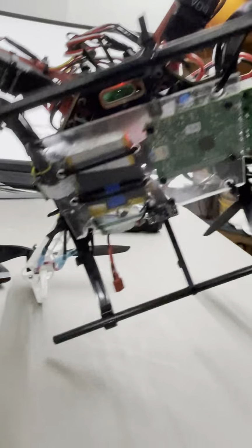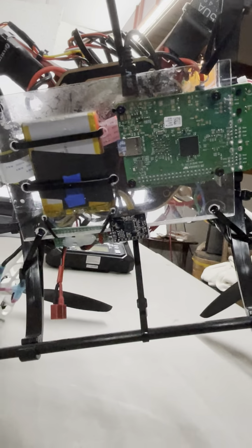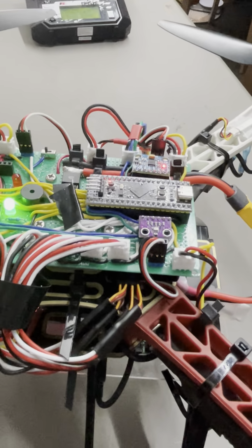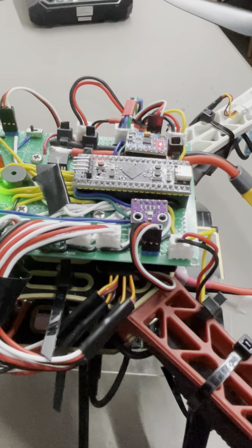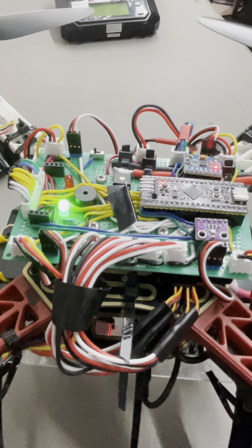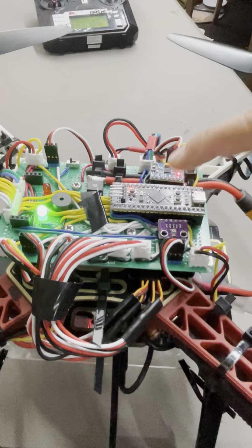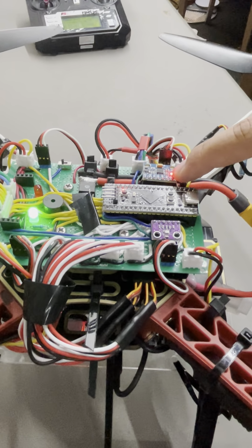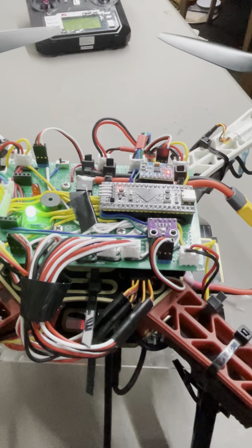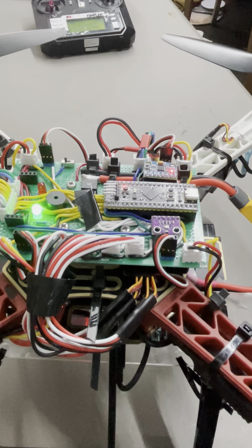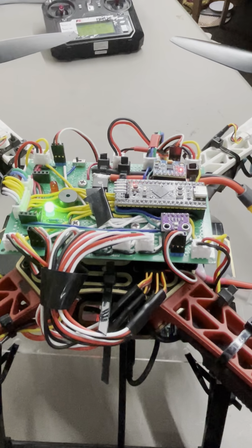And so here's our setup for the Raspberry Pi. We have the Pi connected to a lithium-ion battery and a buck converter. This acts as our power source. On the top, we have our microcontroller that does our low-level operations and obtains our sensor readings. Once we have our sensor readings, such as our altitude, our gyroscope with the angle and rates, we send that over using USART as our serial communication protocol through the RX and TX pins.